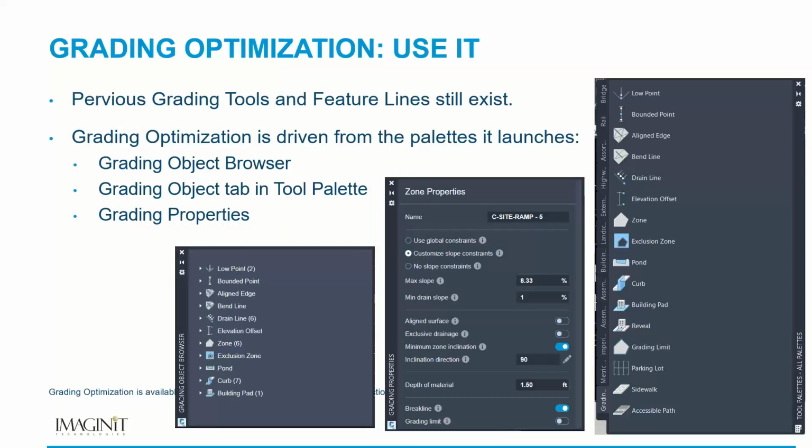When you start using these tools, you start by creating a grading zone, the limit that you're working, and then typically you work from the outside in. The direction that you draw the line work matters. If you start with an AutoCAD polyline that represents a swale or an edge of pavement, it will define the direction that you're grading towards, like a 2%, going from beginning to end. As you start creating elements, they can be dragged and dropped for controlling priorities, very similar to how feature lines work.